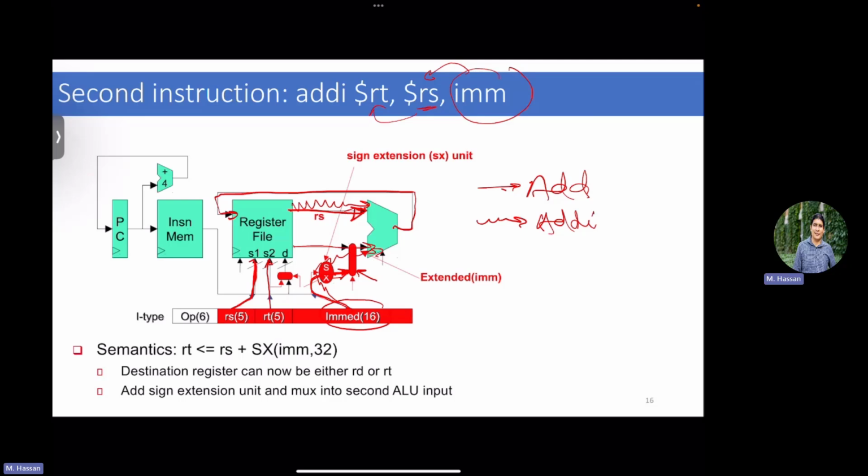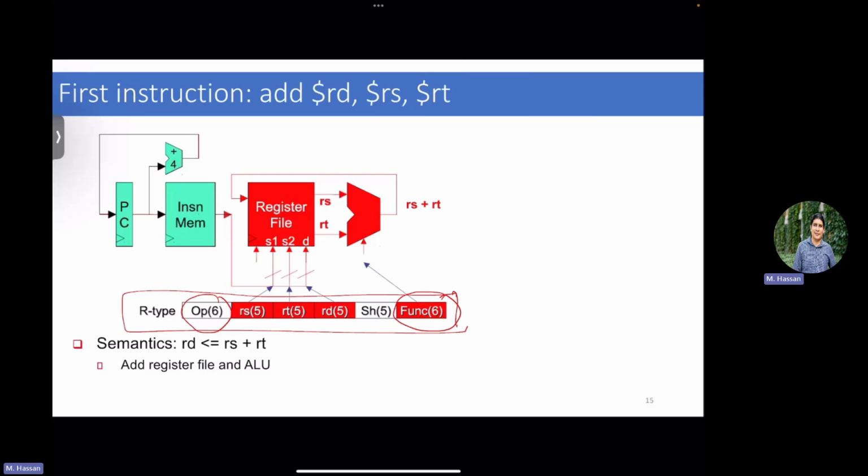Maybe also I should explain this. While we're building this, we'll start by building one instruction at a time and add circuitry to our datapath and controller path. So if I'm only doing an add, I have that. But now I added an add-I on top of an add. If I only have an add-I, then I will not have that mux, right? I will just directly go to that path. But I want to support two types. The processor wants to support two types of instructions. It's why you would have that infrastructure always.